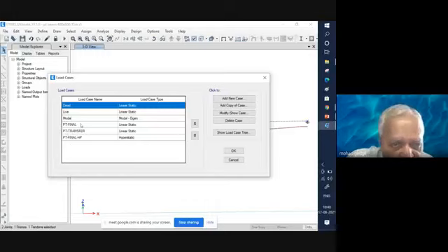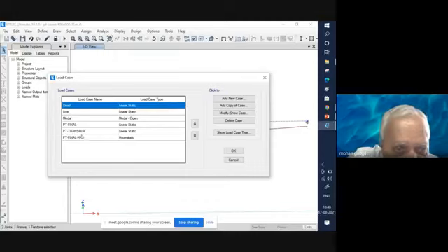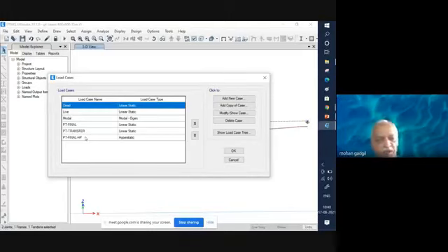The second one is PT final. After all the losses have occurred, you have the PT final. That is your friction loss, creep and shrinkage, and elastic shortening, all put together, which finally give you PT final. And there are the hyperstatic forces: because of the internal indeterminacy in the given structure, the non-PT steel also gets compressed. All these internal phenomena occur simultaneously, and there is a lot of redundancy. So some additional forces are developed which are internally calculated by the software itself; by manual calculation it is very difficult to calculate hyperstatic forces.